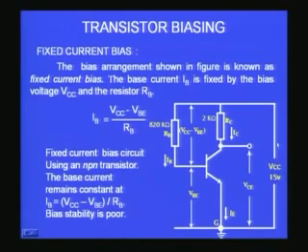Now you can see, as far as this circuit is concerned, there is a voltage drop across the base resistor and there is a voltage drop across the base emitter junction of the transistor, and then you are back at the ground, and therefore the voltage across this plus the voltage across the VBE should together add up to 15 volts according to KVL, Kirchhoff's voltage law. Therefore my IB is nothing but the voltage available across the resistor, which is on this side VCC, on this side VBE. So VCC minus VBE divided by RB, the voltage divided by resistor is current according to Ohm's law.